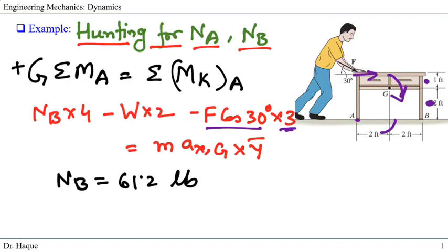We also have the weight acting this direction, so if I take moment about this point, it's also gonna make a clockwise moment, so it's again negative, multiplied by the distance here to here, which is 2. And all we have left is the force NB, the normal force here, and we're taking moment about this point, so the distance is 2 plus 2, 4, and it's creating upwards, so it is creating counterclockwise, so we put it positive NB.